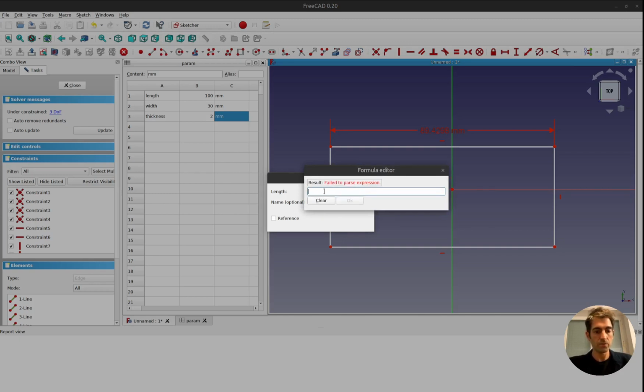Now I want to use the spreadsheet, which has the internal name that I have given, param, like parameters. If I try to write parameters, then it automatically asks me, do you mean the spreadsheet, which is parameter? Yes, I want that. Then it uses a dot, that means inside. Inside I want to use B1. So I start writing B1, capital B, because this is capital B here. Enter. It automatically tells me which is 100. Yeah, I know that.